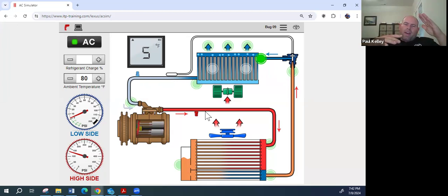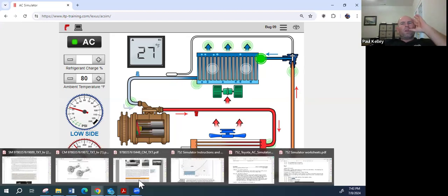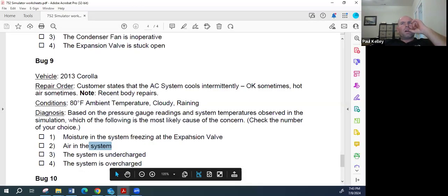Then really after a second or two, the high side wouldn't really be that high anymore, and the low side would still be too low. Exactly right. The moisture is hitting the TXV needle and freezing, at which point the system doesn't really work. And by default, the evaporator and the TXV area get warmer and melted until it makes its rounds again. What was wrong with this car, or what prompted that, do you guys think? What caused that whole situation in this car?